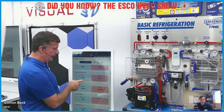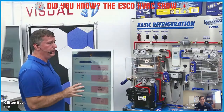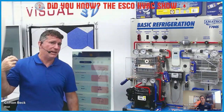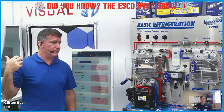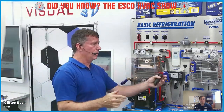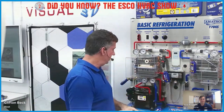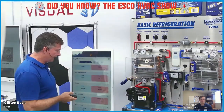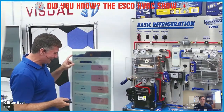Okay. Fair. And for those that are wondering why there is different enthalpy between our supply and our return, I actually have our Daikin ductless unit running at the front of the studio that is blowing air across that would only be hitting this area. So there is a difference between the air behind the unit and in front of it. I'm sure I'll have those questions.